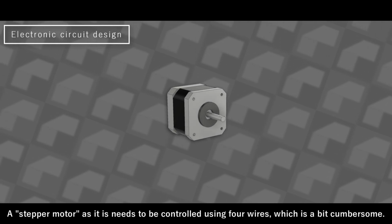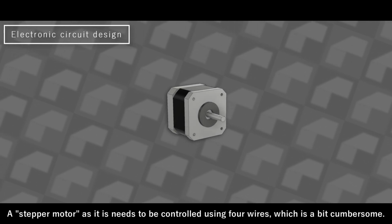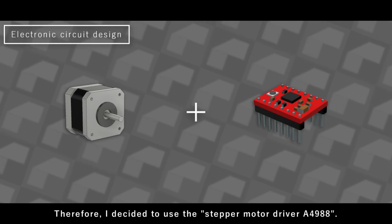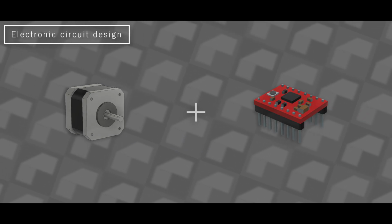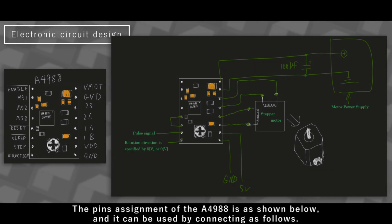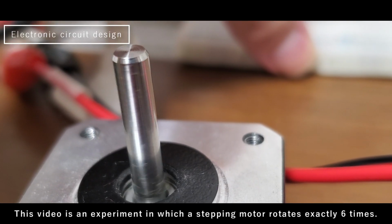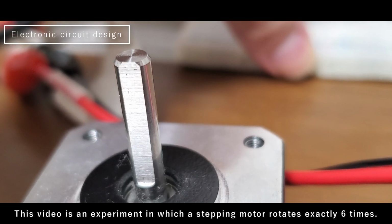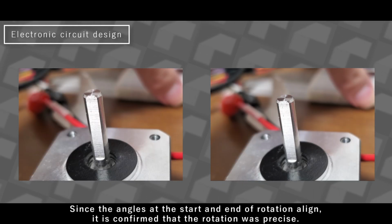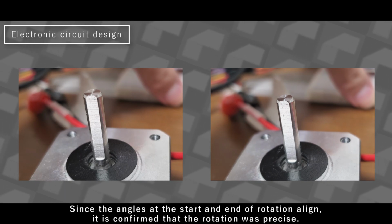The stepper motor needs to be controlled using 4 wires, which is a bit cumbersome. Therefore, I decided to use the stepper motor driver A4988. The pin assignment of the A4988 is as shown below, and it can be used by connecting as follows. This video is an experiment in which a stepping motor rotates exactly 6 times. Since the angles at the start and end of rotation align, it is confirmed that the rotation was precise.